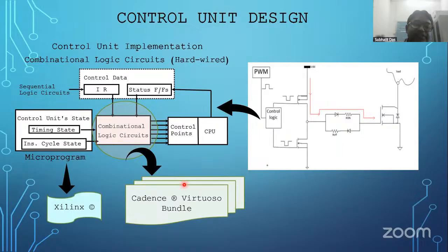But for a combinational logic circuit, whenever we are preparing the circuit, you can change each and every MOSFET dimension. You can make a customized design, because if you need a much faster circuit, you just increase the width of the MOSFET, making the R-on very small. So gradually a faster CMOS will be prepared. That can be done with the help of full custom design. So in Cadence, we are basically using this to make full custom designs.